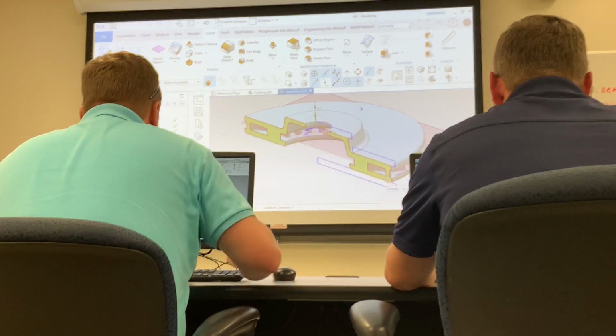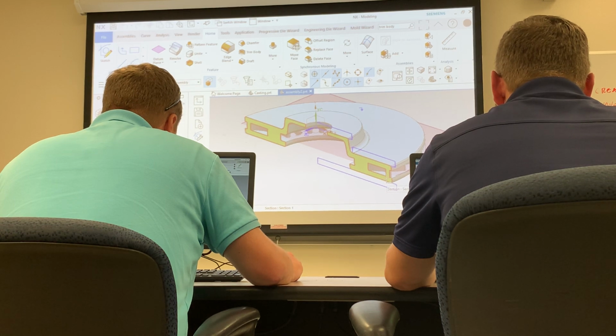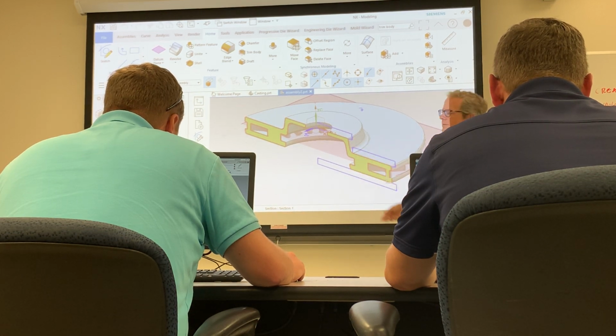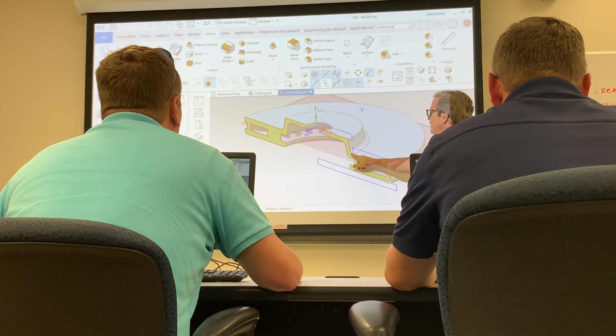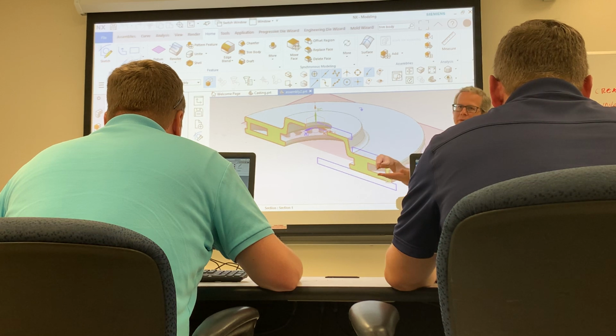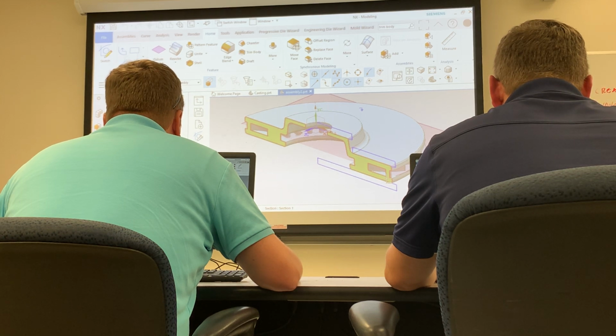So the parts that get machined, it's just going to be this flat surface. So actually the distance of that flat surface to this center plane is what's critical. Then the other dimension is to just make sure that we're trimming off enough, but not too much. This little relief in here is there so that the machinist can go in there and machine that whole surface flat, and then have a little extra for the tool to get parked in while he comes back and does the rest. That's flexible, really dependent on the casting itself, how much relief is in there for that machining operation.